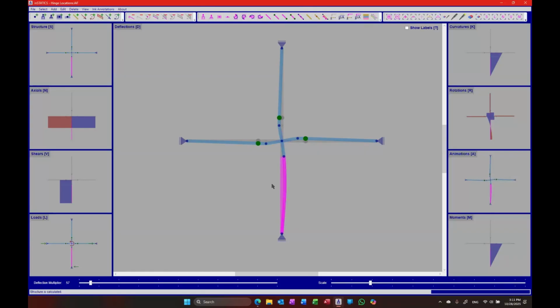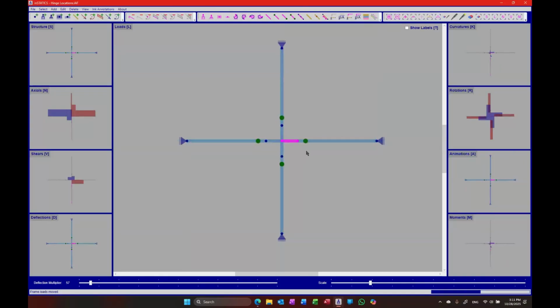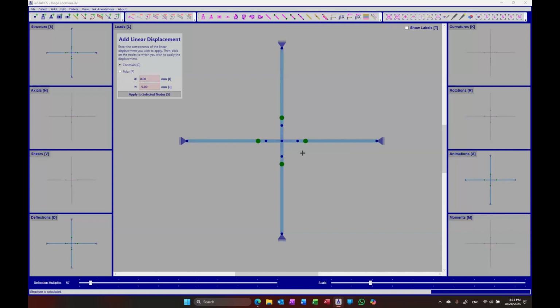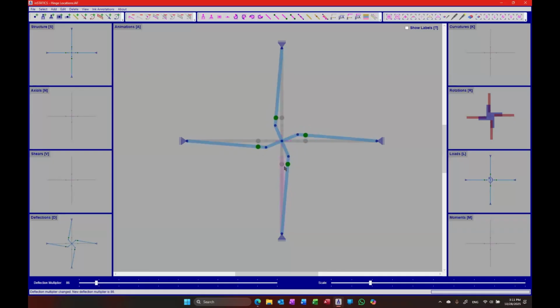So what can we do to see that deformation? I'm going to remove the load, and instead I'm going to put a rotation there, like 0.01 radian. And if we look at that, you can see that this joint now, because we also broke this end, turned that into a hinge, it's free to rotate, which tells us that by putting the hinges on the connecting elements, we have the flexibility to decide exactly how the load will flow.